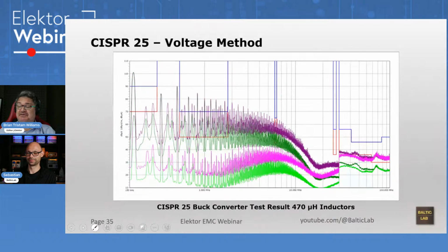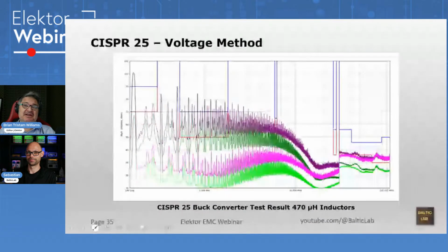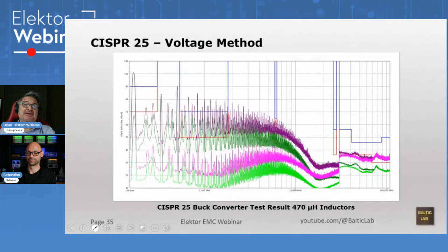And even after FCC compliance, the board had a ferrite bead on the low voltage AC power input. And the entire motherboard was shielded in stainless steel. And still, you could hear that computer clearly thinking on your AM radio. And you could even hear it when you were typing, despite shielding like that.